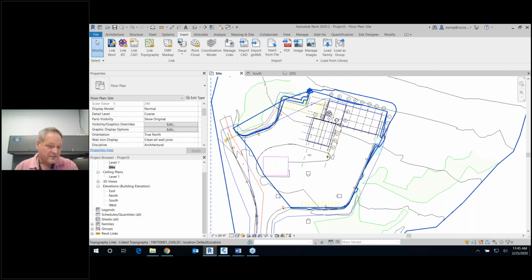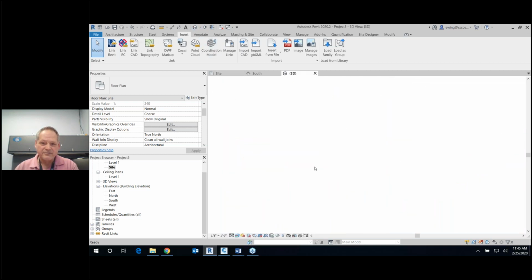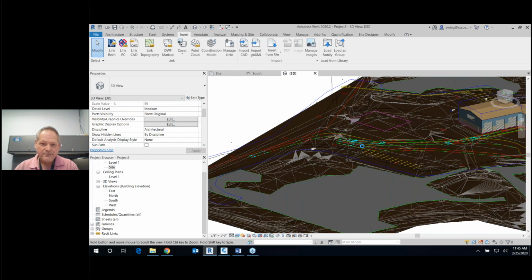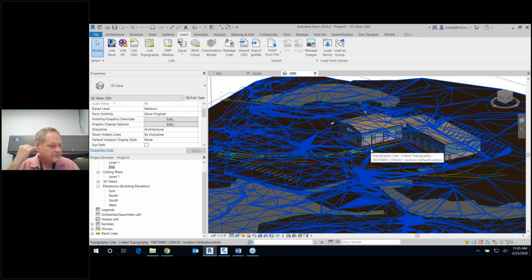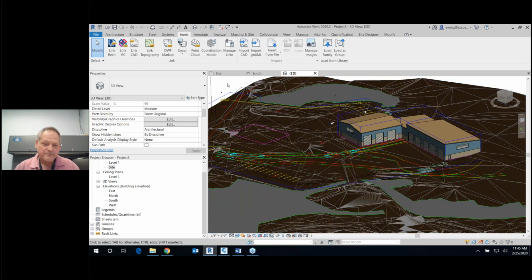So I found that if I quarantine a site model, if there's any latency or any artifacting going on, it's only going to be in that model. And again, if people want to bring in tractor trailers and stuff into their site model, go ahead. Now I have a model that I'm not going to open unless it's deemed that the buildings are off.